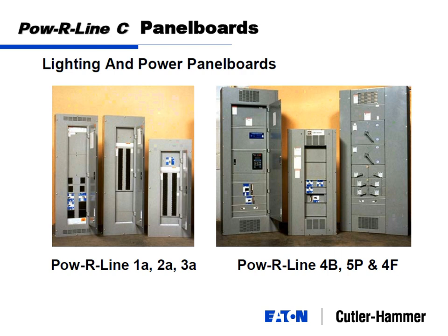It's just a convenient means to distribute power, again, more efficiently. Because if I've got my main switchboard here, and I've got a bunch of lights and receptacles I need on the other end of the building, rather than feed all my loads, I run one set of large cables to a big power distribution board. From there, I can take her one step down into my lighting receptacle or individual load type panels.